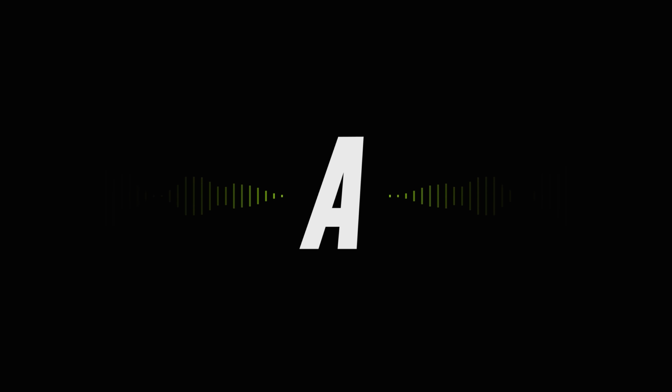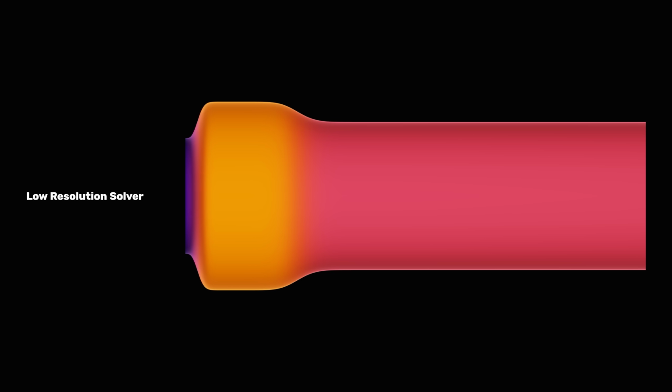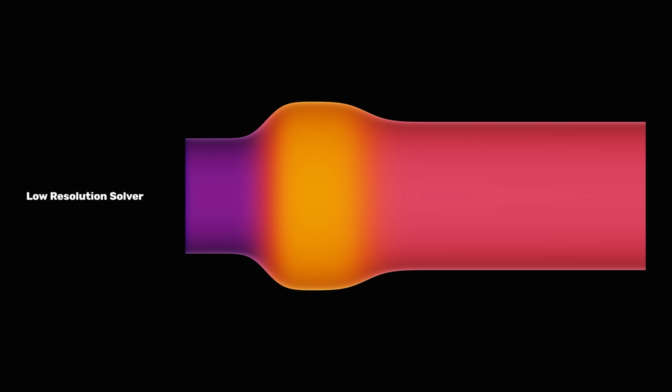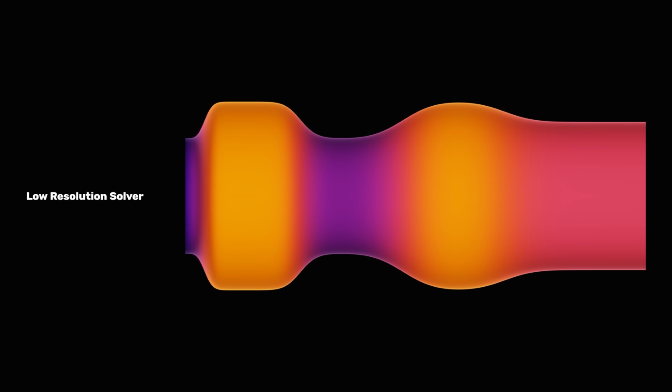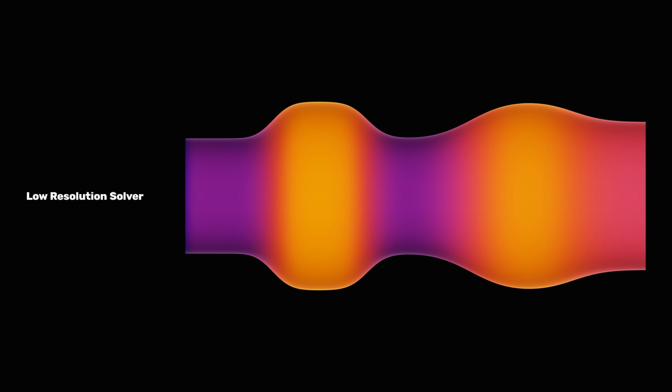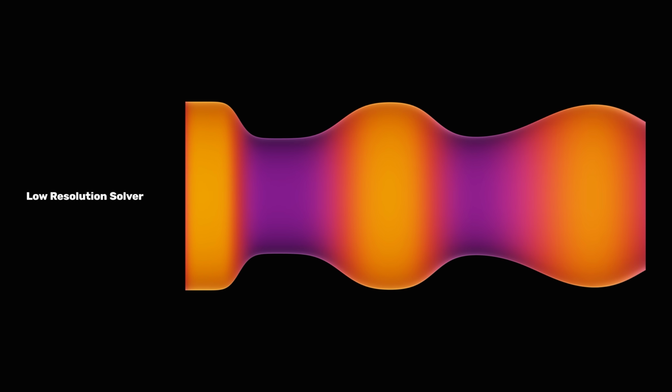The most obvious issue is that it sounds a bit muffled. A more precise way to put it is that the output is missing high-frequency detail, as though it was low-pass filtered at some point. This is unfortunately just a mathematical reality of how fluid simulations work. In this case, we are using a very simplistic partial differential equation solver, which introduces a lot of artificial dissipation into the solution. By artificial dissipation, I mean that the signal is becoming rounded over at the edges as though it's worn down or eroded.